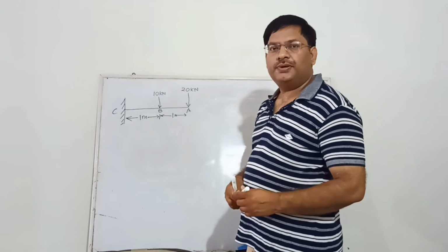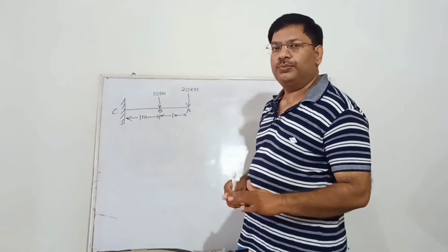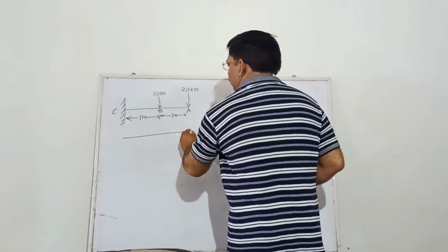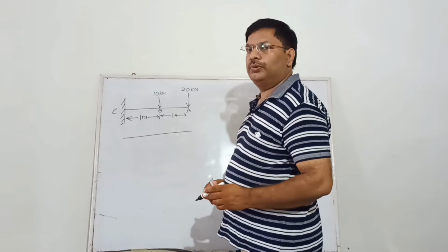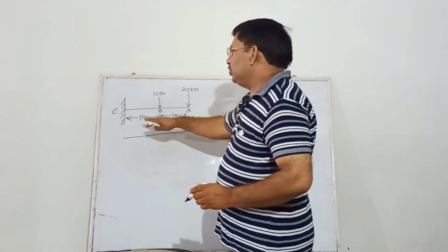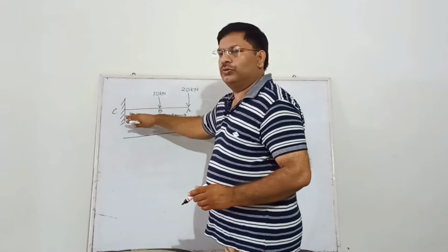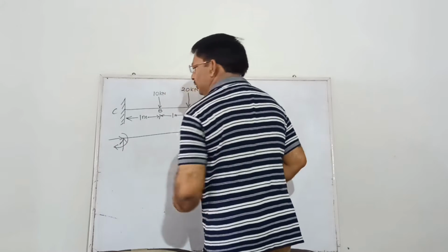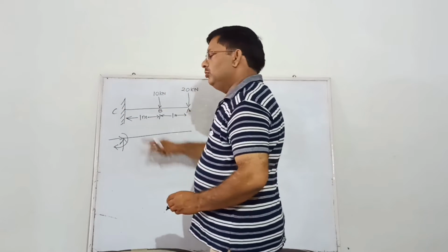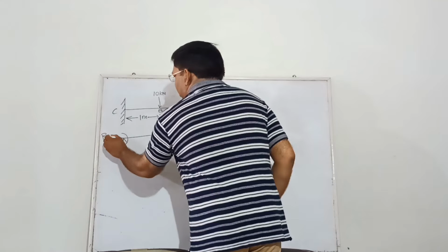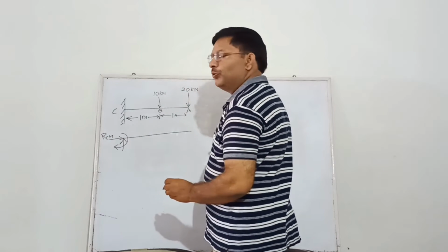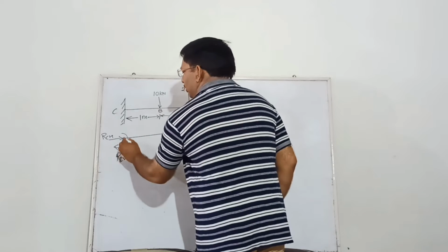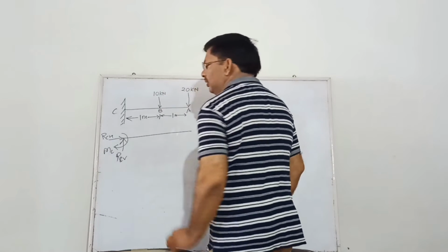So our first step is the same, that is we have to draw the free body diagram for this beam. We will have to remove all the supports, and in place of those supports we will have to draw the reactions. So you know that in case of fixed support we have one vertical reaction, one horizontal reaction and one moment. Since the point is C, we will take this reaction as RCH, that is horizontal reaction at point C, RCV, that is vertical reaction at point C. Similarly the moment, we will give it the name MC.